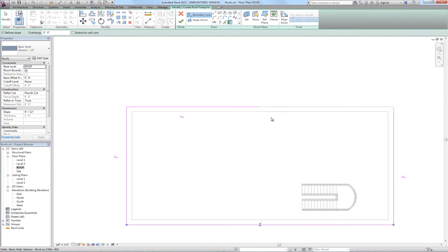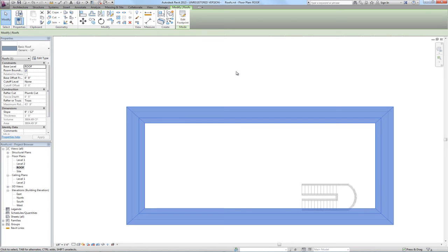We notice because we have two sections of walls here, there's a piece missing in our sketch. I could click this wall and it would go ahead and create another line. Otherwise I could use the trim command, so we have the ability to trim these sketch lines. Now, without doing anything else, I'm just going to go ahead and finish this so you can see that we select the roof command, we pick the perimeter of the building and finish, and then we get a roof.